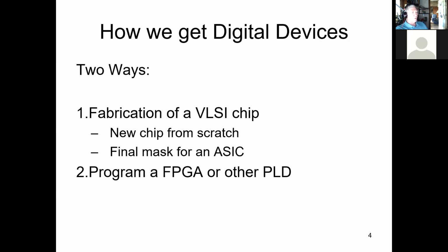The only other way we do anything is an embedded project with an embedded microprocessor, where you're writing the microprocessor code. But more and more, most of our digital devices have an FPGA and a microprocessor. Often the microprocessor will be built into the FPGA, but it might be a standalone chip. In any event, combining a microprocessor and an FPGA is pretty much how things are going to go.